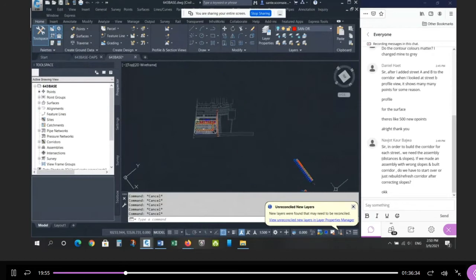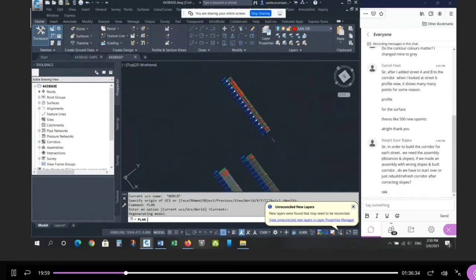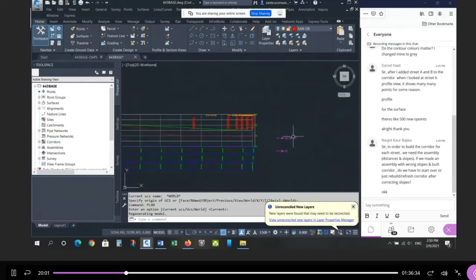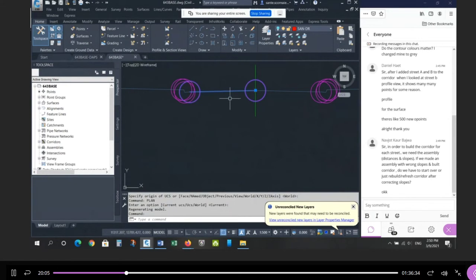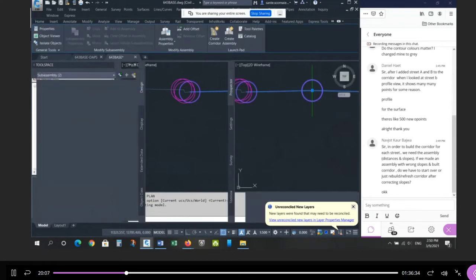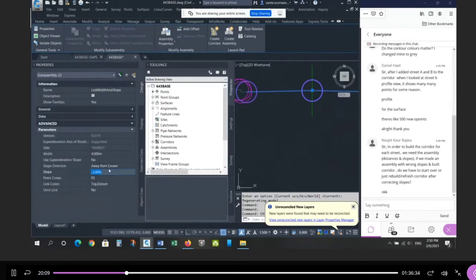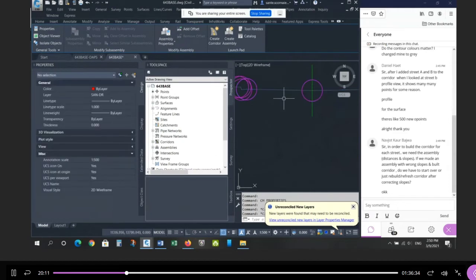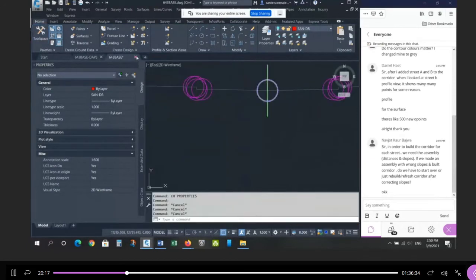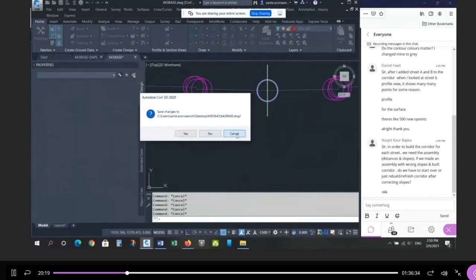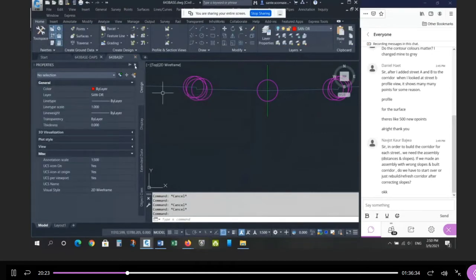If your corridor, let's say you mess this up, right? So let's suppose you made an error here. Here's a common mistake, okay? See this slope and this slope here? In the past, I've seen some students, instead of -2, they put +2. See how now there's a low point at the center of the road instead of a high point? Okay, if that's what you did, and then you find the mistake later, you can always fix it.